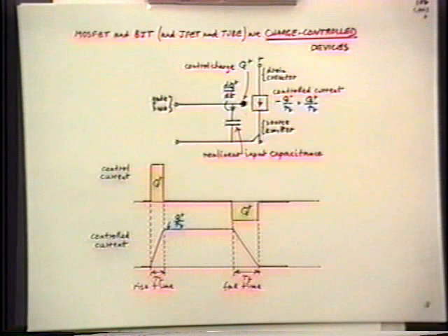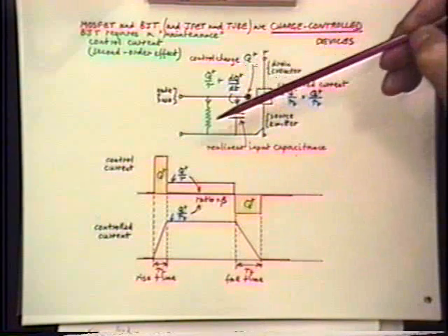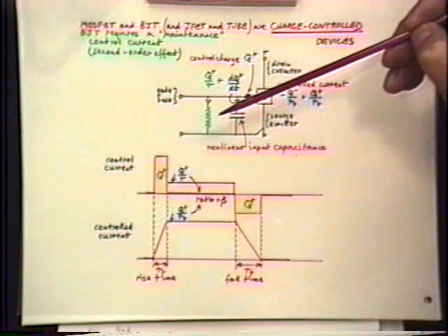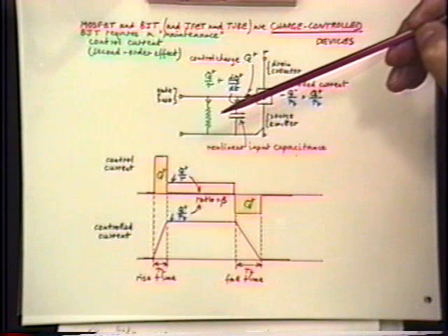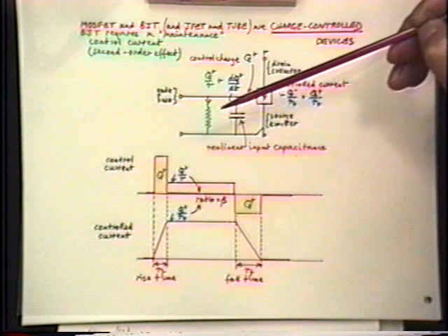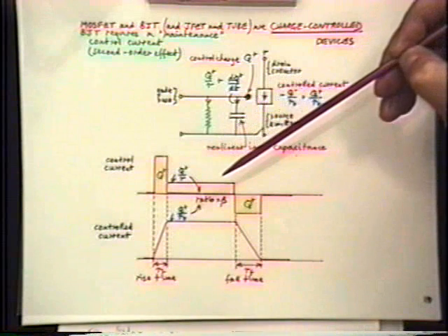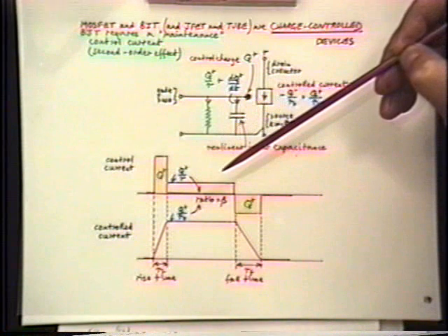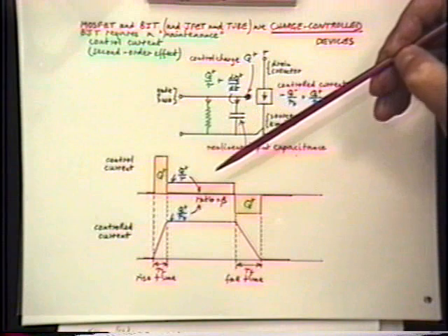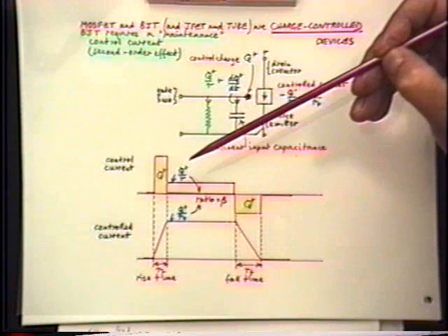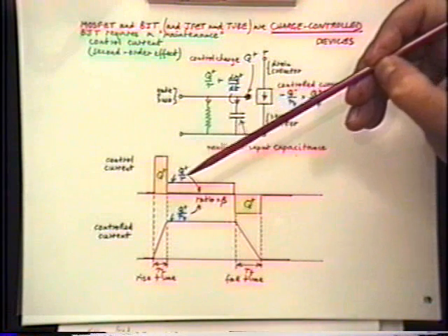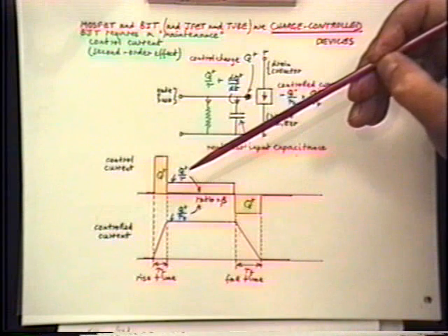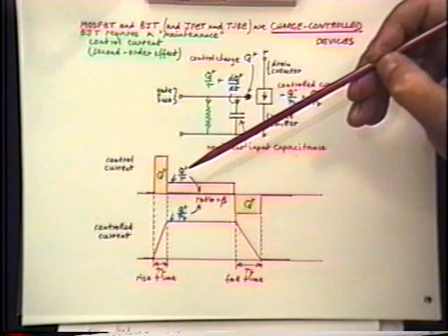However, in the BJT, recombination must be accommodated in the model. This is done by addition of a resistance which accounts for the steady state or DC base current. The corresponding non-zero maintenance base current appears in the graph below. The value of this current is the total positive charge of holes, Q plus, divided by the mean lifetime, tau, of hole electron pairs in the active base region.